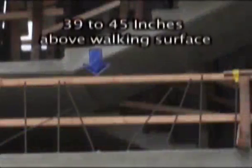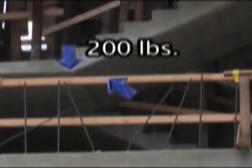OSHA requirements for guardrails are that the top rail must be between 39 and 45 inches above the walking surface, be at least 1/4 inch thick, and be able to withstand a force of at least 200 pounds applied within 2 inches of the top edge in any outward or downward direction at any point along the rail.